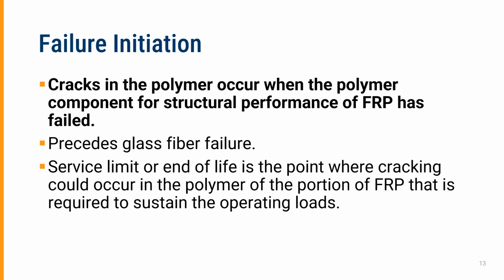The service limit, or the end of life, is the point where cracking could occur in the polymer of the portion of FRP that is required to sustain the operating loads.